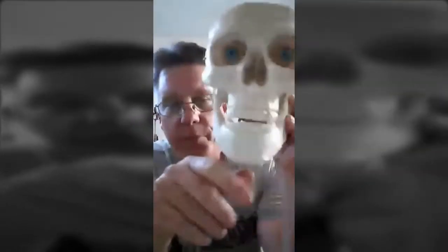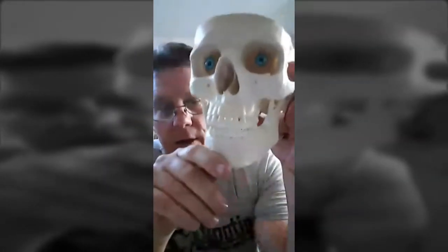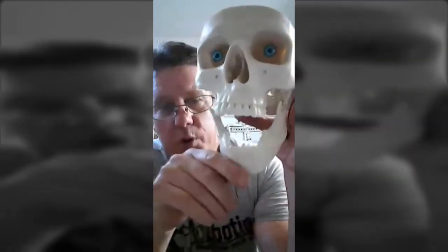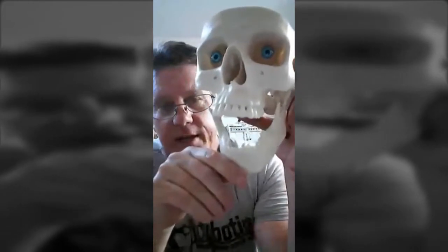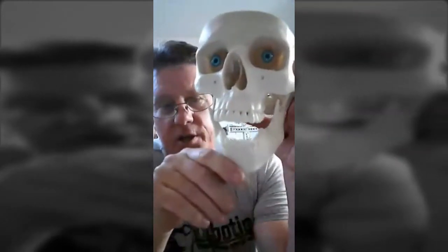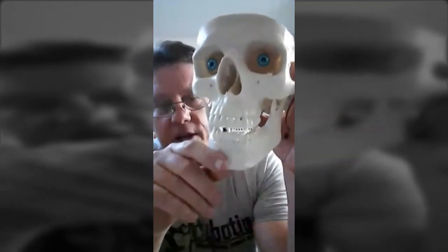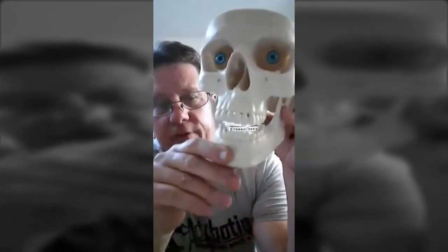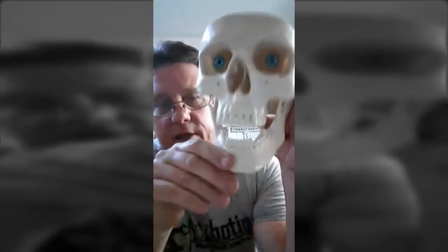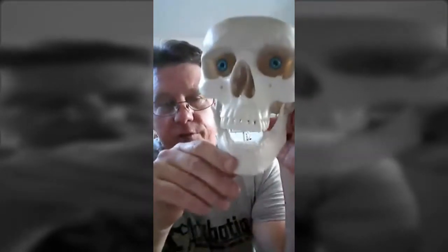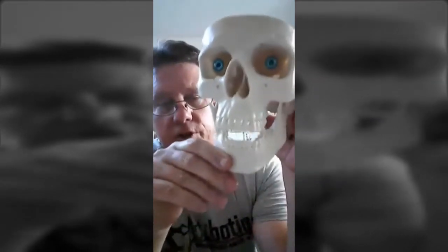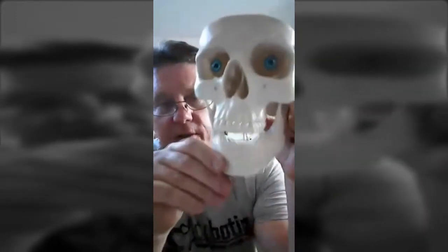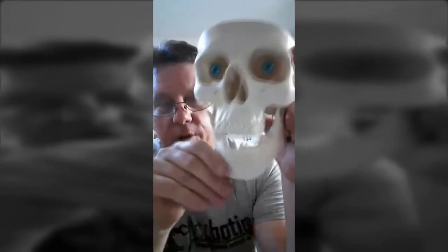But for me, driving the jaw about this much is more than enough movement. I think that gives a pretty realistic look. And when you set your jaw, you're also going to want to make sure that it's not driving all the way shut. This makes a ton of noise. It's bad enough dealing with servo noise, but the jaw hammering together like this, to me, is a whole lot worse than the servo noise.